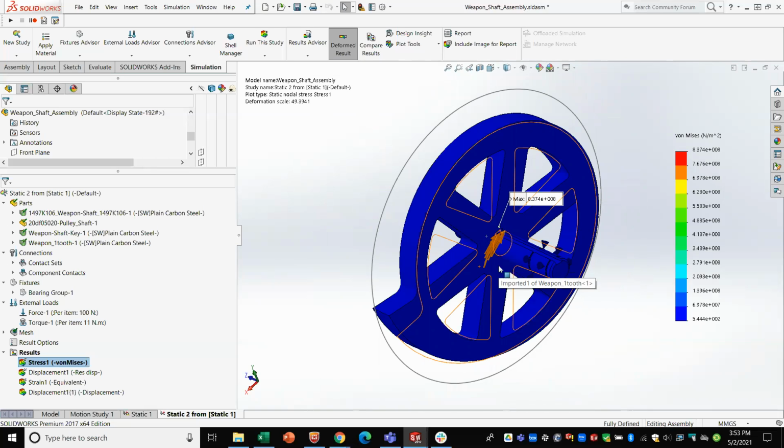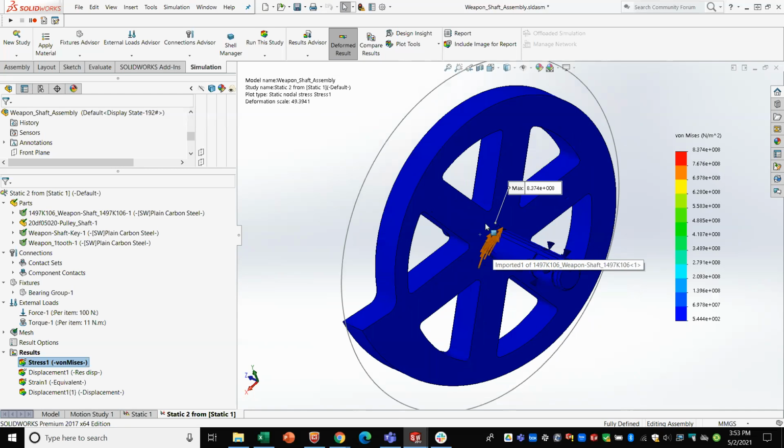Yeah, if you're looking at making this out of, say, for example, S7, if this disc is going to be made from S7, your failure strength on S7 is going to be like 1,000 or even 1,200 megapascals. Oh. So it's way higher.